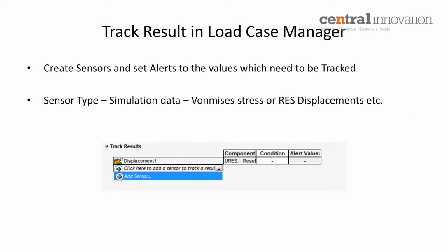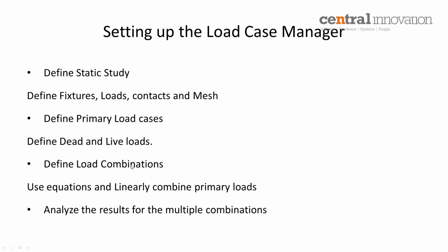I'll open up SolidWorks. So this is the sensor I was talking about. You can see it from here. The sensors can be added from the screenshots. You can see here, I added a displacement sensor. And before I show the SolidWorks, these are the steps I have to follow for the load case manager.